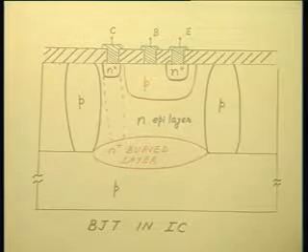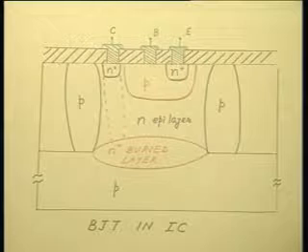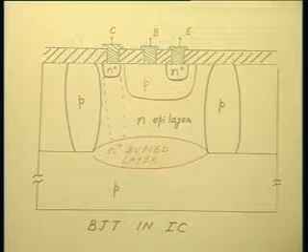So, since your p-type diffusion has a considerable depth, that means it extends in both ways as well. So, even if your original isolation window was small, there will be considerable spread on both sides, and therefore, you will have larger area requirement. Okay? That is one drawback.